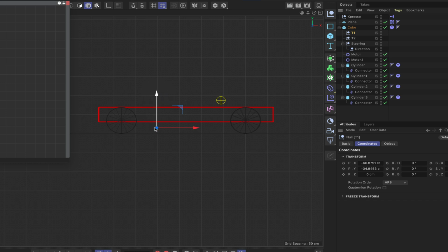And this is where we're going to place our particle emitters. So they're a little bit in front of the rear wheels. So we'll drop that into T2 and just zero that out. That makes that easier that way. Let's have a look where T2 is. Oh, I've done that the wrong way round. Not the way to do it. Right, okay, T1, drop T2 into T1 and zero it out. That's the way. Okay, fantastic.